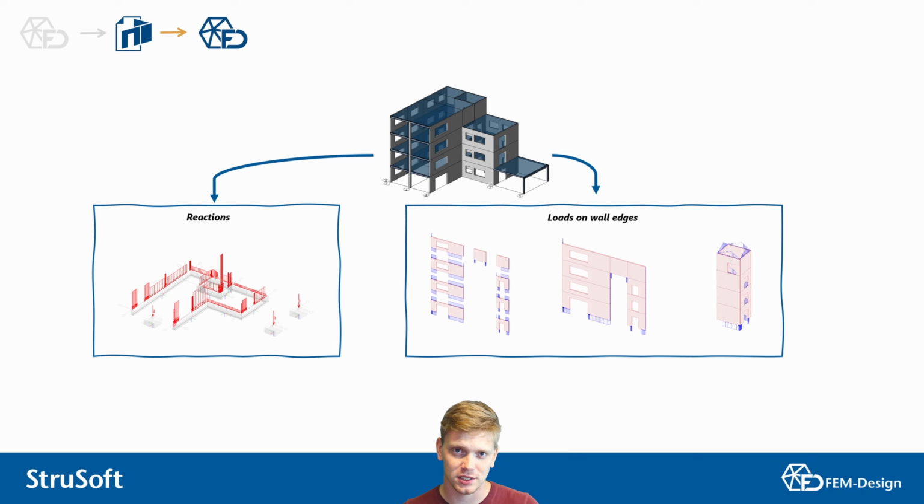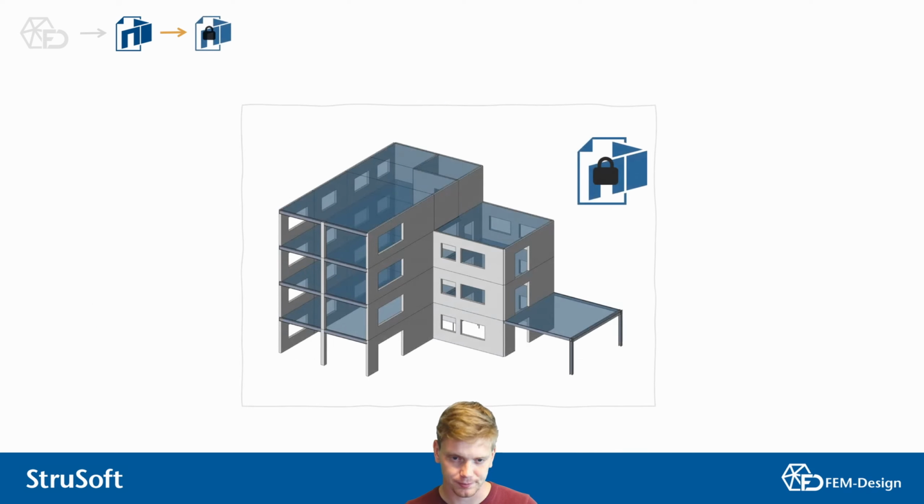Another main export option is the exporting back to FEM-Design. This is really helpful for workflows. It will allow you to export reactions so you can do foundation design checks based on the prefab treated data, and it will also allow you to export all the walls with the loading along the edges. Now this is one where we allow for 3 different types of export, and they all differ in how they would suit your workflow. And they're all available through easy export, and you can also get this just specifically for a specific set of elevations, wall elements directly from the viewer.